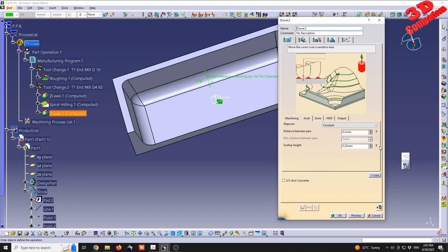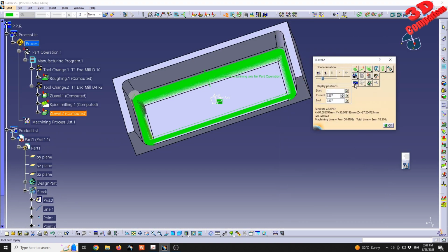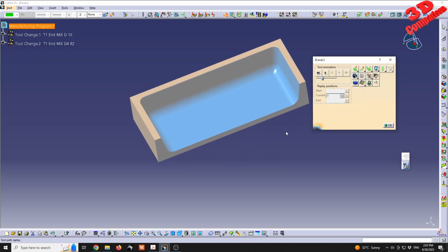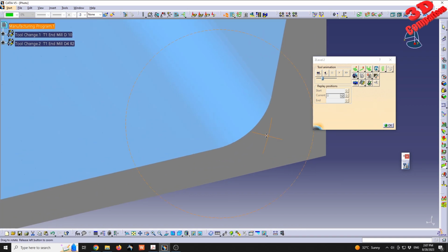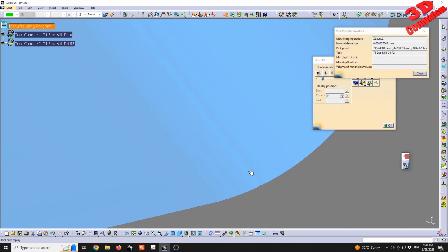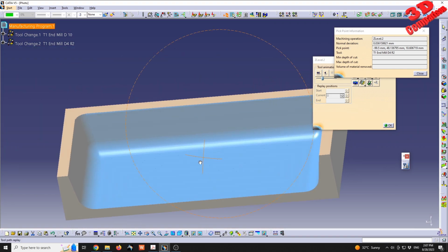And if I go again and go directly on the camera, over here we can measure those. So as you can see, we still have a small slope, but that is not as high as it was. So 0.03 will be that height. We can further adjust that with various machining parameters. But for this case study part, 0.03 millimeters for that is more than enough.